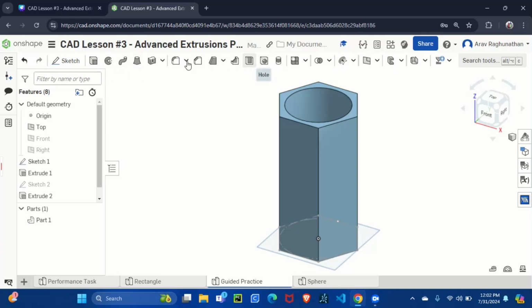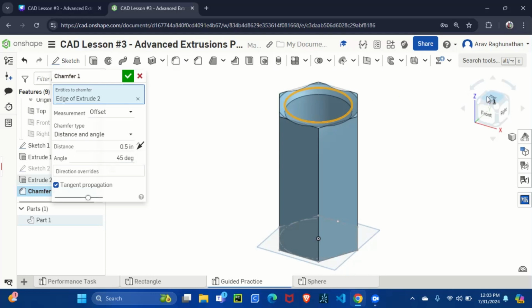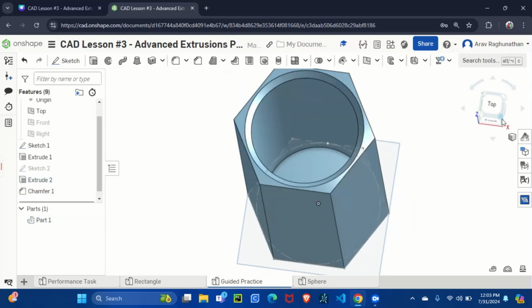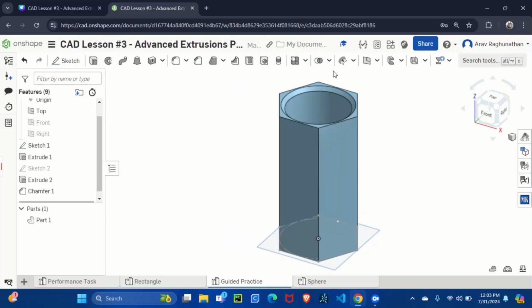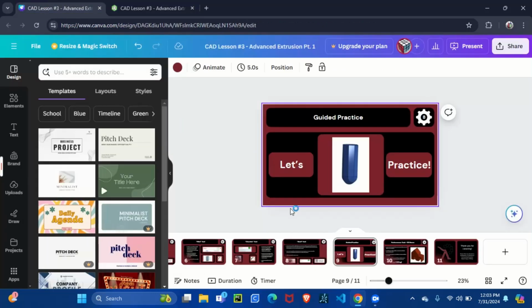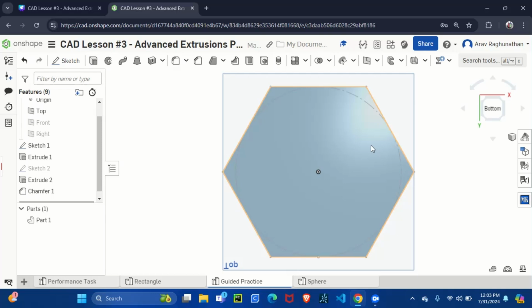So click on, remember, how do we do this? We click on chamfer, and then we click on the edge we want to do. And obviously we can reduce it. So we'll do 0.25, for example. Once you look at that, you created a nice little chamfer rim. You can create a nice little rim here for the extrusion. So now let's go down and we'll create this revolve. You see there's like a circular kind of thing going on at the bottom. But first, obviously, we got to make sure we have all our parameters for that.